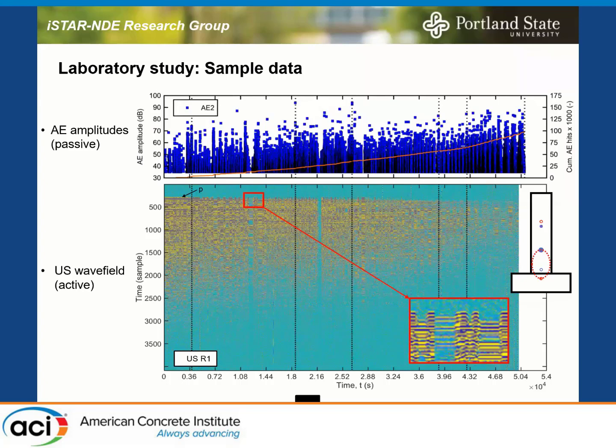Yeah, you can. First of all, I've done some field work where we embedded these in the structure too. If the owner will let you do it, you drill in, you push the transducer in, and you put a special slightly expansive grout in. That will create a good bond. That works well. We did that on a historic structure and collected months' worth of data. That is absolutely possible. But it doesn't matter. You can do it with surface mounted sensors as well.